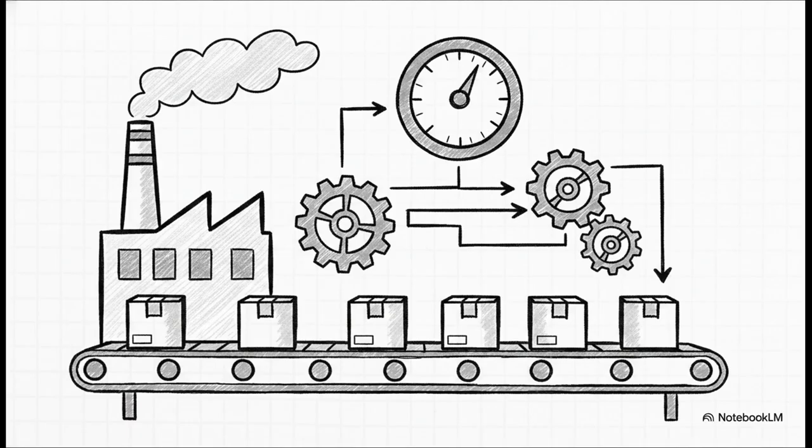We need to make sure we can actually build this thing flawlessly at scale. The outputs here are heavily geared toward process control, like the process flow diagram, the process failure mode and effects analysis, or a PFMEA, a pre-launch control plan, and yes, even packaging standards. Because really, what good is a perfect product if it gets totally destroyed during shipping?